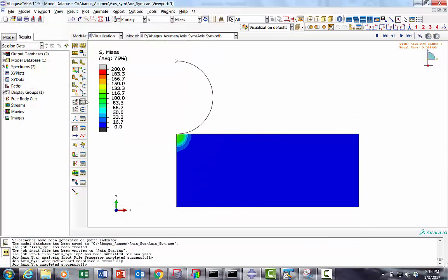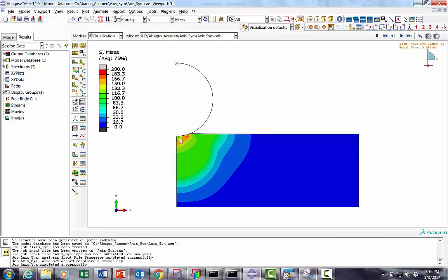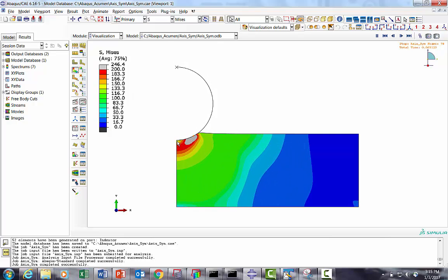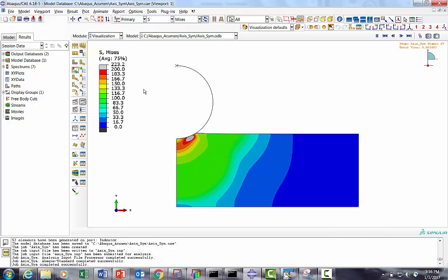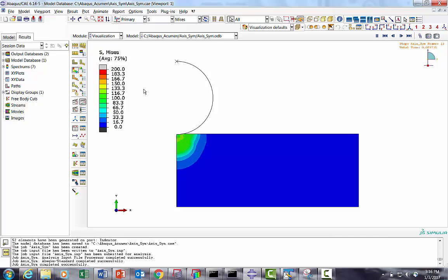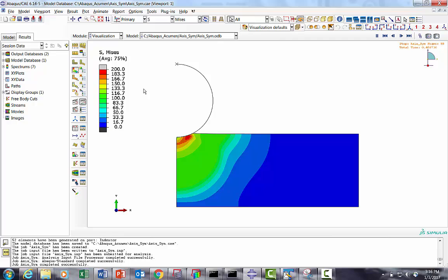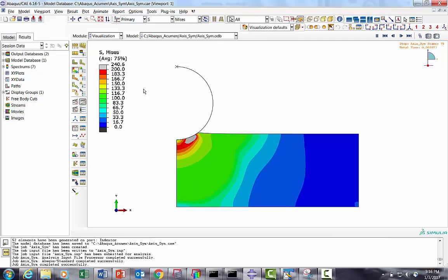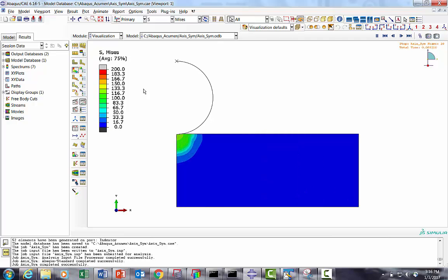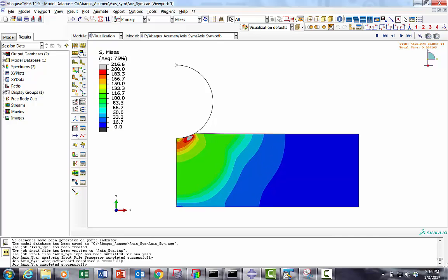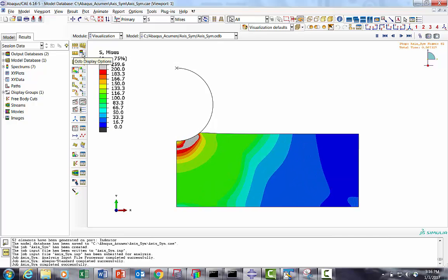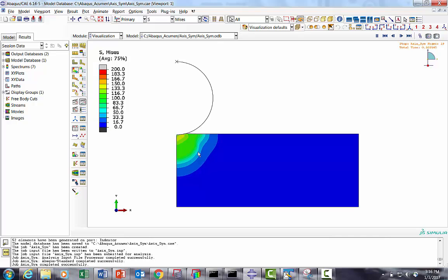So you can see the Mises stress, how it is pushing, and then you can measure plasticity and how much the diameter changes. Now once you solve this problem, a 3D problem converted into a 2D continuum problem, while post-processing you can always give results in 3D. That also looks good when you present it, because a lot of effort from those who developed these axisymmetric elements went into solving our major pain. So how to get these 3D results?